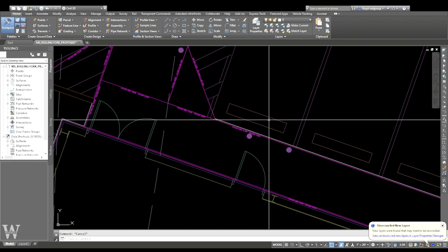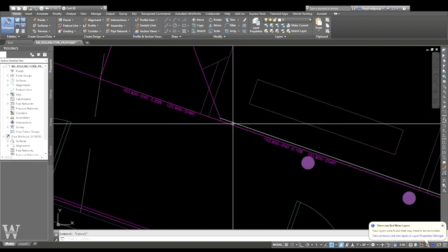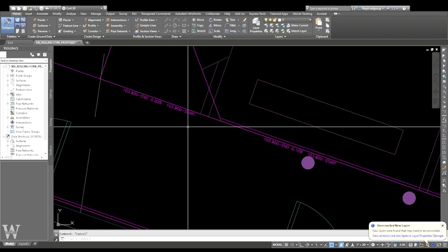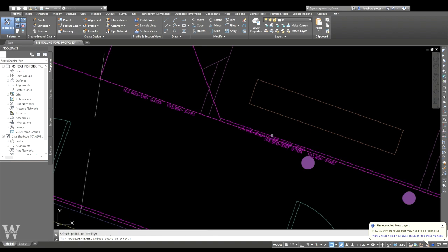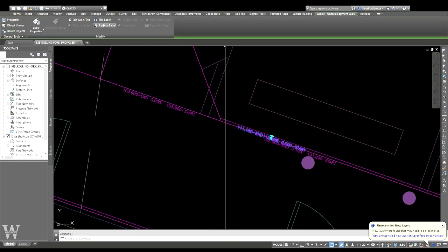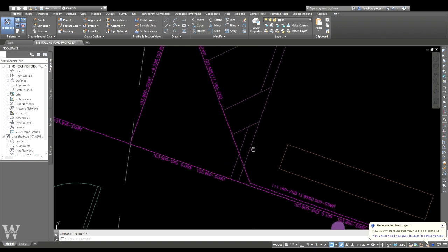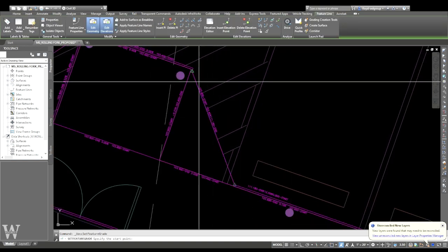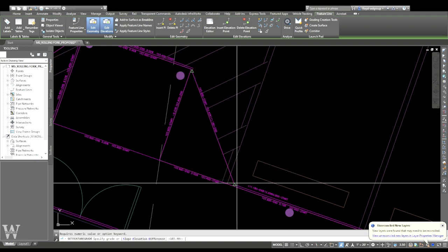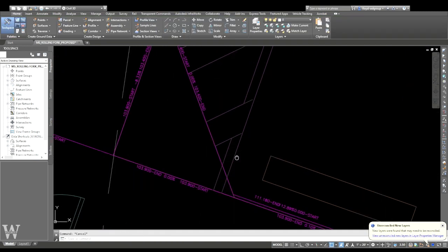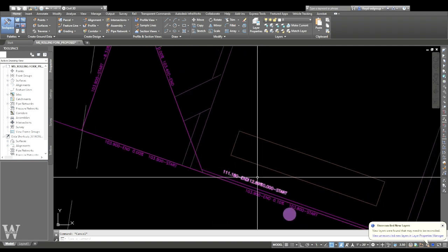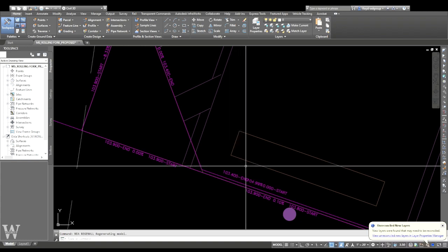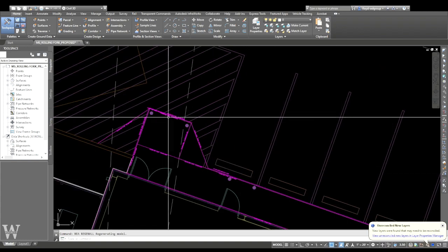Okay? All right. Now, let's do feature line from objects here to get the bottom of the sidewalk there. Now, if we did it right, it should have picked up that elevation. And it picked up an elevation. And what happened was, I did something weird right here when I went here, grade 0, and didn't get it right. Now it's right. This didn't update, right? Like I told you, sometimes it does, sometimes it don't. Do a quick regen, and it picked it up and it fixed that in.